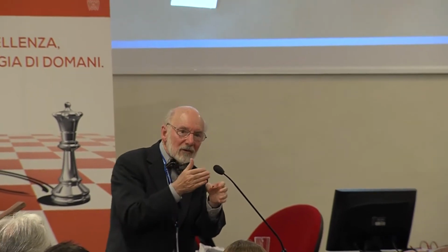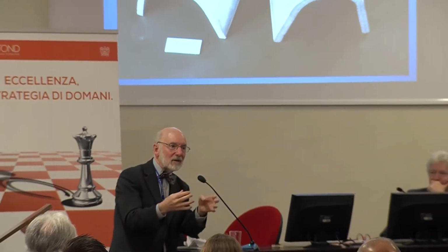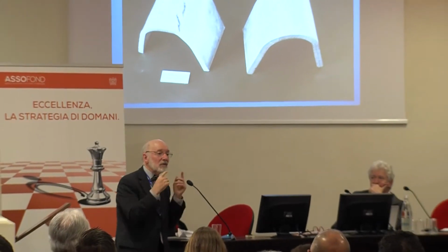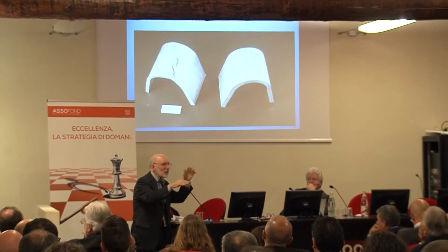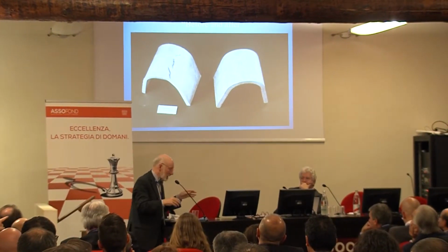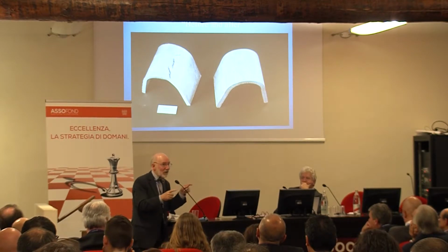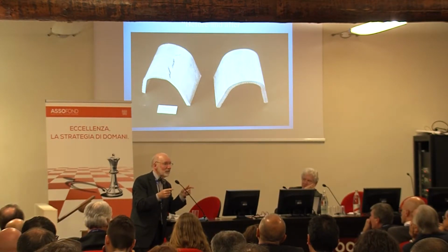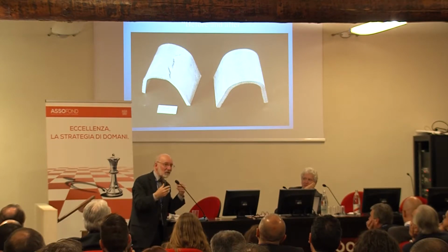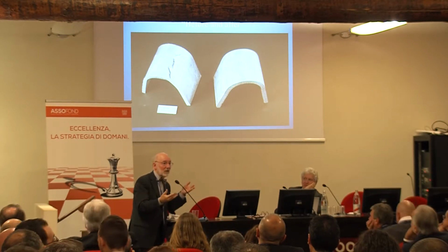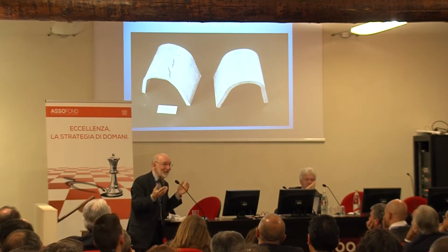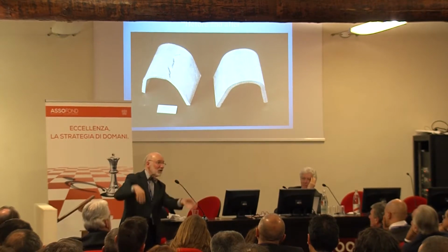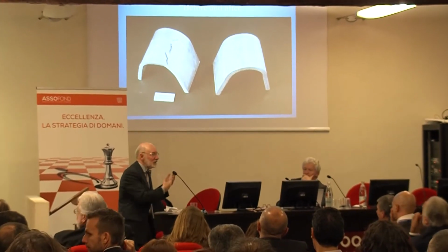You would expect with a 3-point bend to have the cracks exactly along the axis of the bend, but they're not there. These cracks are random cracks. They're just occurring anywhere, in all directions. And that tells you that this is not a metallurgical problem. These are cracks which have been introduced into our metal by a random process called turbulence. It's just that we've folded in and we've messed the liquid about, and we finish with random cracks.